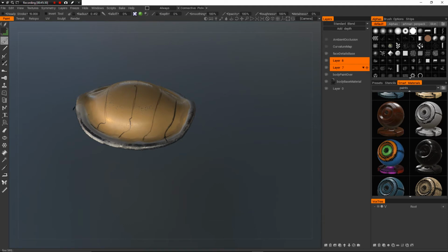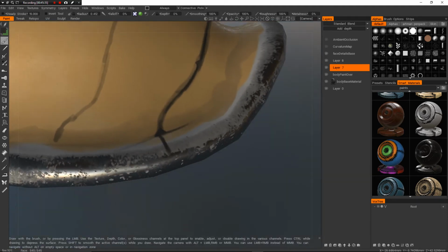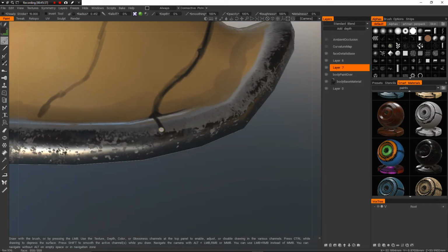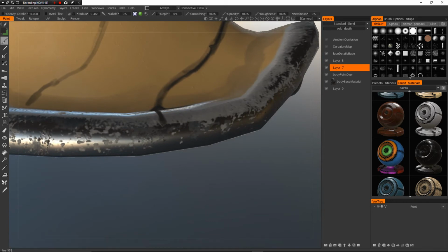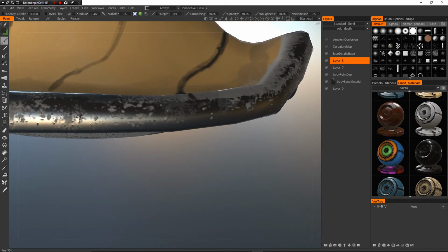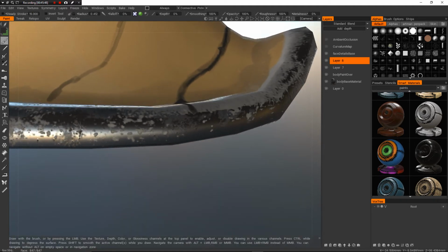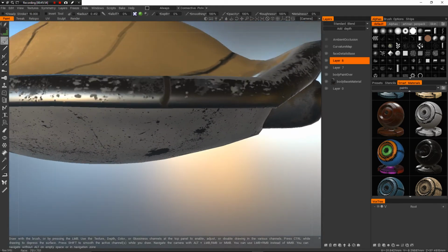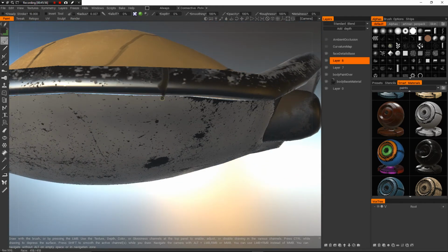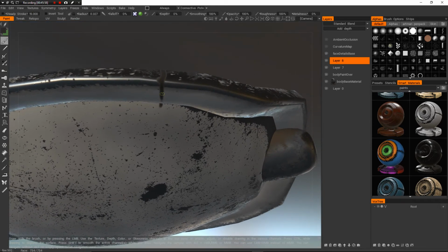If you remember, this layer here is clipped to body paint over. So I won't only be able to paint on this paint, so I won't be able to paint on the metal underneath. But in this case, I also want to set my metalness to 0. Oops, I'm on the wrong layer. So if my metal is set to 0, you'll see that I can kind of paint out the metalness in these cracks as well. So now it's just a regular diffuse texture.